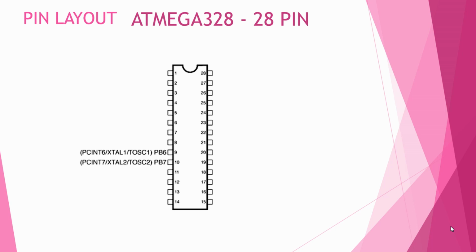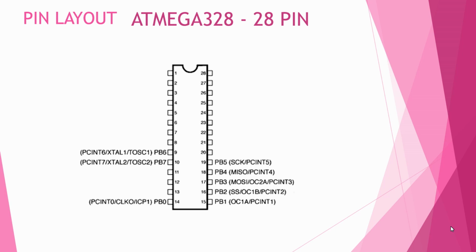Pin 9 and pin 10 are the crystal oscillator pins through which we can provide a clock frequency to the microcontroller using an external crystal oscillator. The maximum clock that we can provide to this microcontroller is 20 MHz. And next, we are going to see the port structure of this microcontroller.